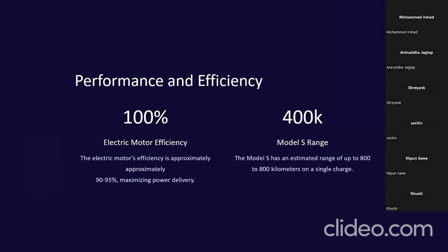So in terms of motor, the motor efficiency is not constant throughout your driving. It can change based on different RPM, different torque, and different power input. But you should remember, whatever motor you are selecting, and whatever conditions it's running for, it should have an overall efficiency of more than 90%. So in the Tesla Model S, the efficiency in overall driving ranges between 90 to 95%.